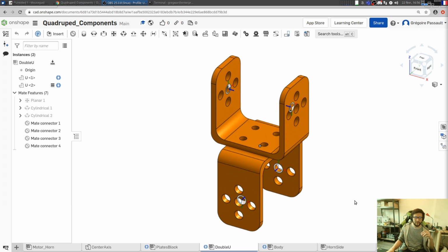So the first requirement, and I think it's a good practice anyway, is that you split your robots in what here I call components, which are just blocks that are jointless, and create a top-level assembly in which you just import those components and connect them with joints. So the top-level assembly is just those components that are instantiated as many times as you need them, and connected with the joints you will use, and nothing else actually.